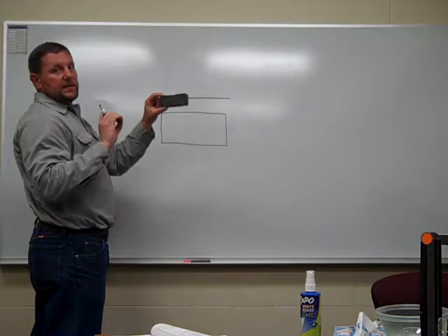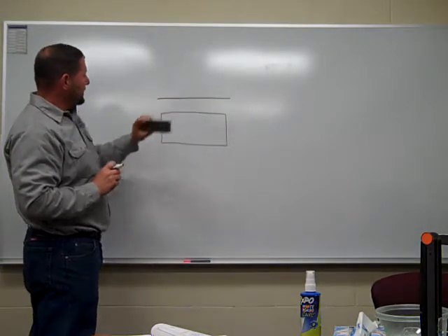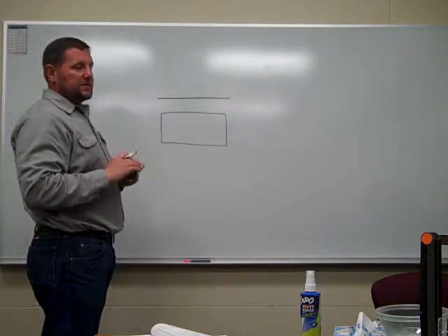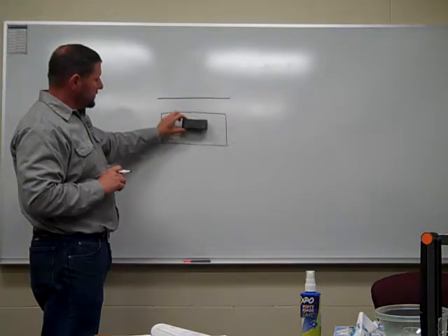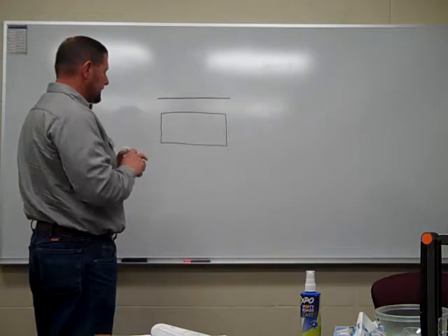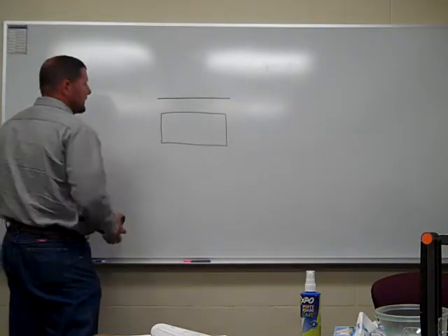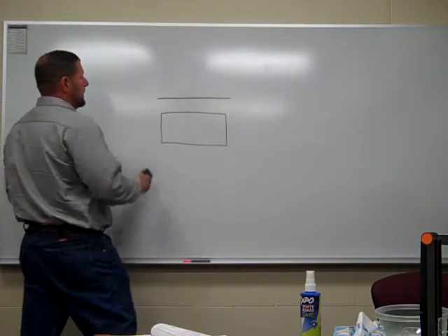It's what you can see on the object. So these solid black lines are what they call visible or object lines. You're going to see a lot of them on the print. In this view, that's what you can see. So as you look at all these prints, those solid black lines are all visible object lines. That's what you can see in that view.